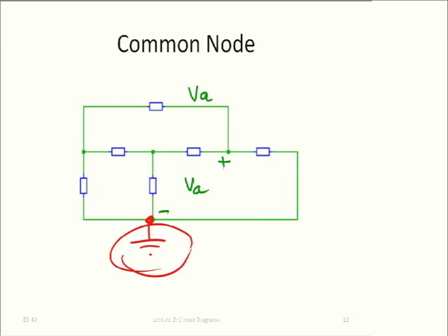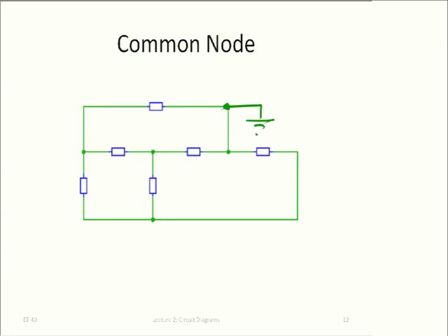It's just any volt at any node in my circuit here, at any node like VB. What I really mean is the voltage between here and wherever I put that ground signal. And it's really totally up to me where I'm going to put the ground symbol. I could just as well have put the ground symbol here. Okay?